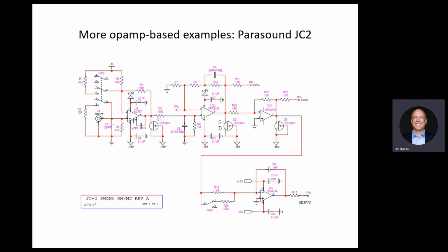You'll notice the same trick as the Linear Technology one. All the stages are biased into class A by putting in a transistor, which is a current source. A current source essentially takes a push-pull circuit and forces it to conduct in one direction. So it sort of turns it into a single-ended circuit with a high impedance load. A lot of technology, but it does linearize the circuit a tiny little bit.